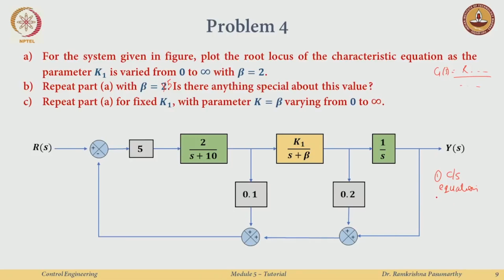For that I will do the signal flow graph analysis, where the transfer function had 1 over delta times the summation of P_k delta_k. I do not really need to do the entire transfer function. What I just need to know is what is in the denominator of the transfer function. The characteristic equation, what was it, 1 plus G(s)H(s), if I had a k outside, equal to 0. This is just the denominator of the closed loop transfer function.